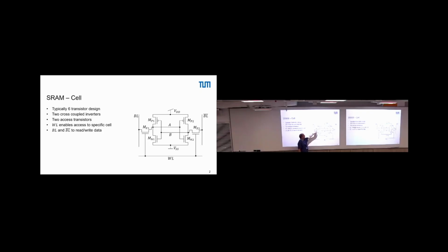So if you would directly connect here, we always would be connected to the bit line. We cannot attach multiple cells to the same bit line. If we completely disconnect, we cannot write the inner state. So these are actually the access transistors. They are not responsible for storing any data, they're just switches. And then we have these CMOS structures here and here. What is this inner structure here?